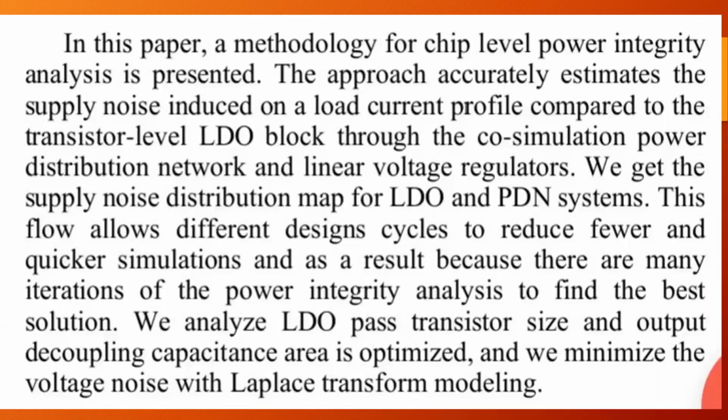In this paper, a methodology for chip level power integrity analysis is presented. The approach accurately estimates the supply noise induced by a load current profile, compared to the transistor level LDO block, through co-simulation of the power distribution network and linear voltage regulator. We get the supply noise distribution map for LDO and PDN systems.